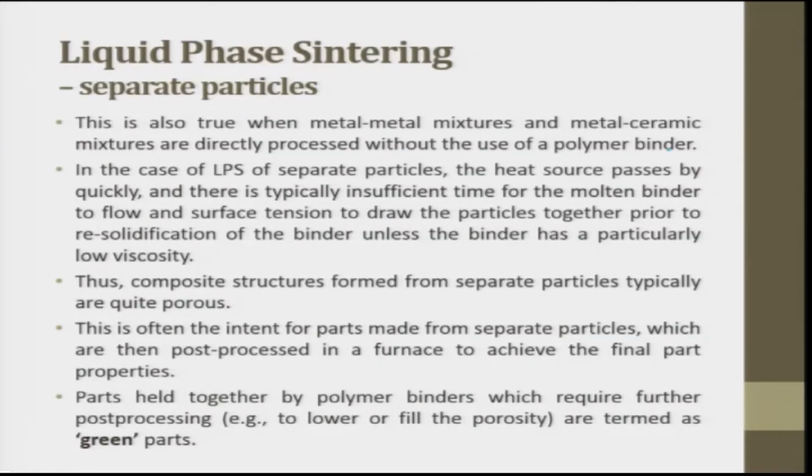In this case of LPS of separate particles, the heat source passes by quickly, and there is typically insufficient time for the molten binder to flow and surface tension to draw the particles together prior to resolidification of the binder, unless the binder has a particularly low viscosity.